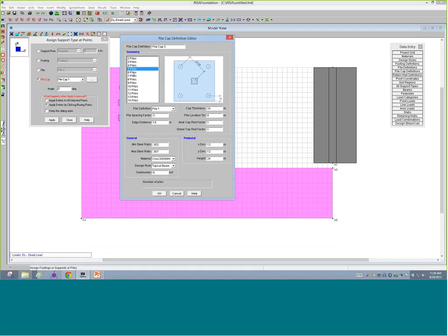So you have some different formats. Here you can see what a 2-pile looks like, a 3-pile, and these are just some standard formats for pile caps. In our model here, we'll just pick a 6-pile. I can tell the program what type of pile to put underneath it. So this pile cap has 6 piles, and it can be either the square pile type or that round pile type, whatever properties I defined in those. We'll just keep it as that round one we just set.